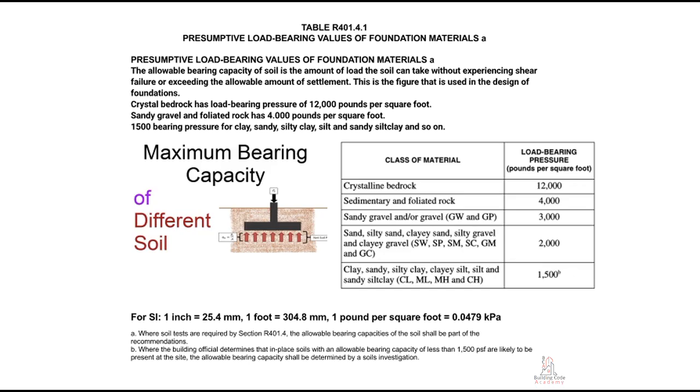Table R401.4.1. Presumptive load-bearing values of foundation materials. The allowable bearing capacity of soil is the amount of load the soil can take without experiencing shear failure or exceeding the allowable amount of settlement. This is the figure that is used in the design of foundations.